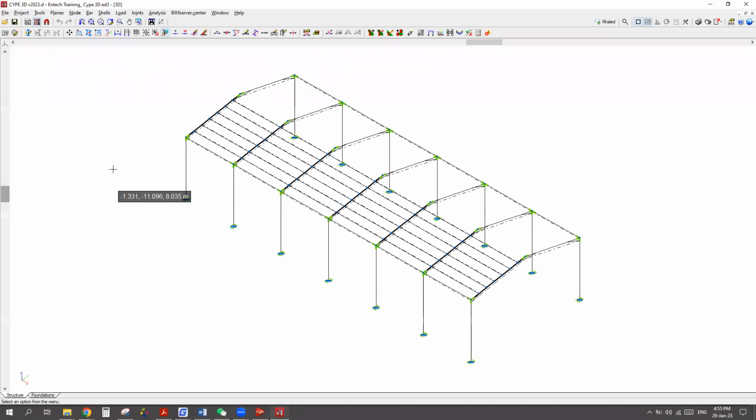Let me go to structures, and here I have the project, and here I have the dimensioning units. If I click on that, the dimensions of reinforcement can be shown as millimeter, the length as meter, and also dimension with millimeter. Accept. So the option is here under project dimensioning units. Let me regenerate the foundation drawing to see if you have the millimeter or not.